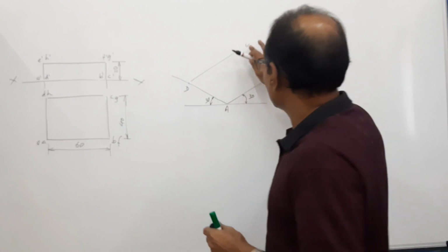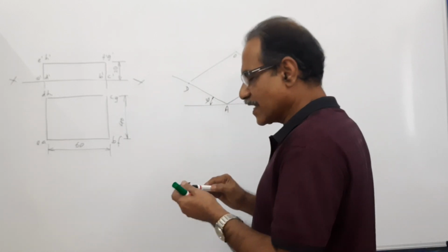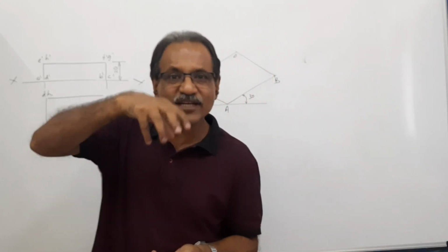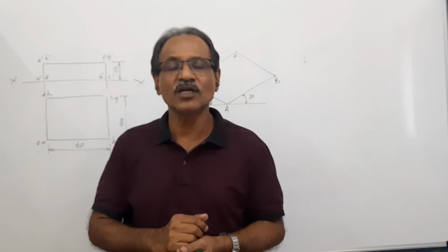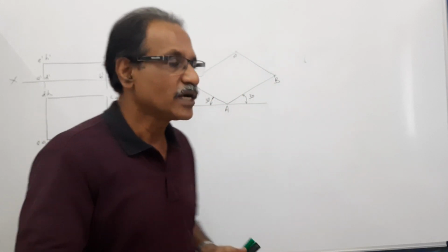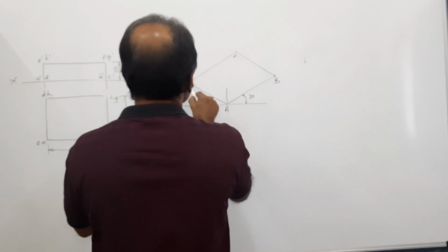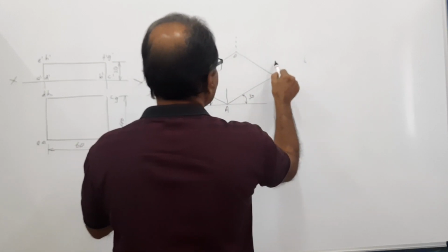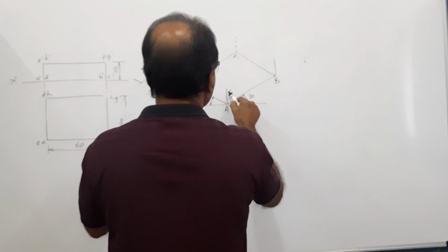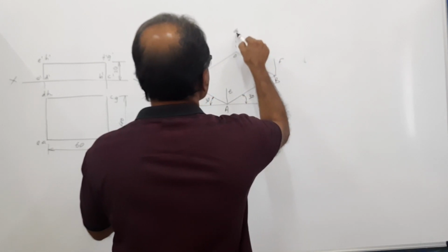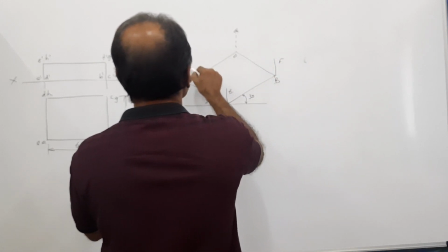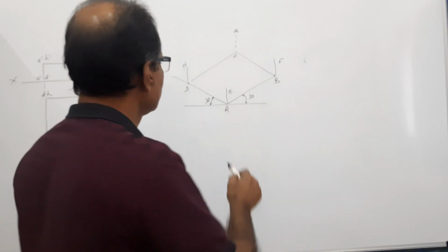After getting C, consider the height of the block. How much is it tall? 20 mm. Draw vertical lines at all the four corners whose height is 20 mm. E, F, G, H. Connect them.